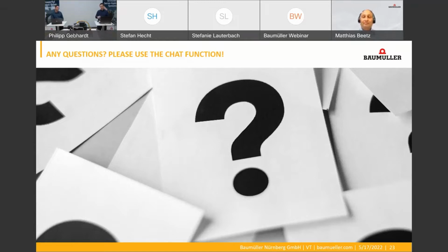So the main effort is to install ProDrive, our engineering tool, and then you just have to order ProSimulation. Therefore, you get an installation license. This license you have to import in ProDrive, and then you can build up your first simulation. So maybe I think also around half an hour, then the installation is done.